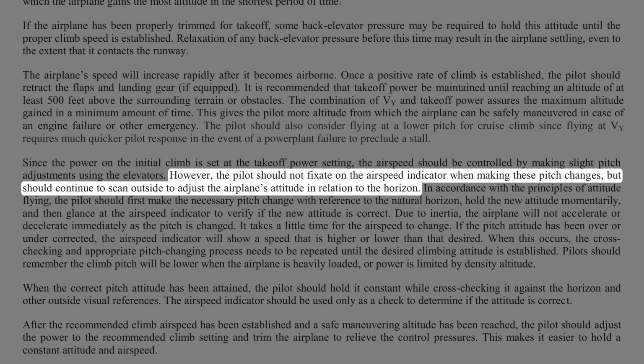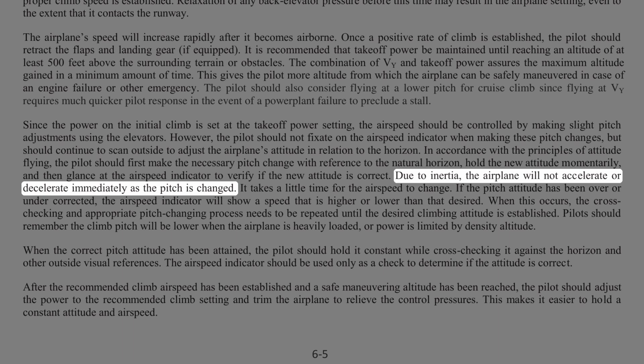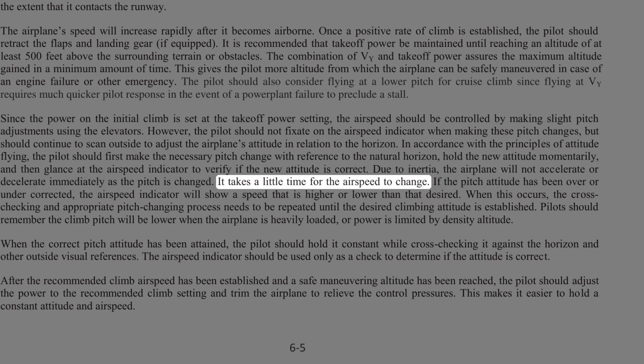However, the pilot should not fixate on the airspeed indicator when making these pitch changes, but should continue to scan outside to adjust the airplane's attitude in relation to the horizon. In accordance with the principles of attitude flying, the pilot should first make the necessary pitch change with reference to the natural horizon, hold the new attitude momentarily, and then glance at the airspeed indicator to verify if the new attitude is correct. Due to inertia, the airplane will not accelerate or decelerate immediately as the pitch changes. It takes a little time for the airspeed to change.